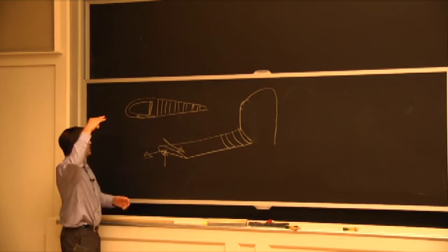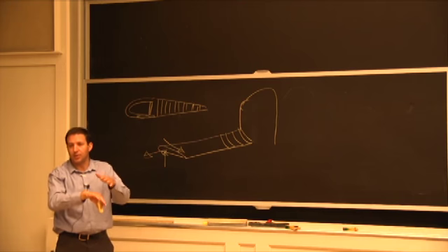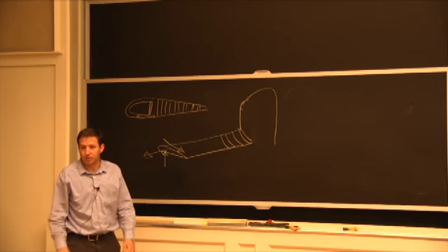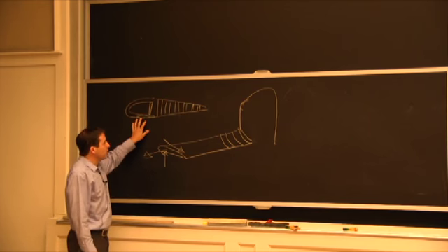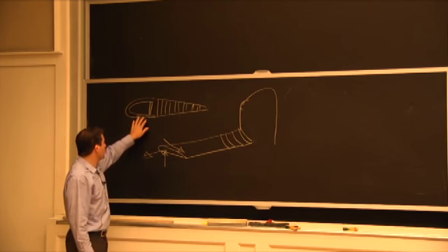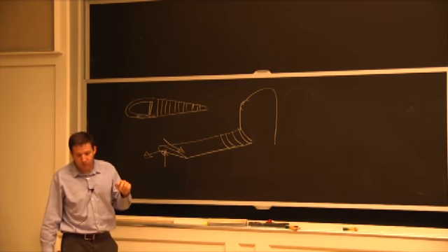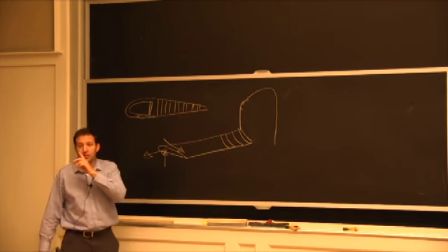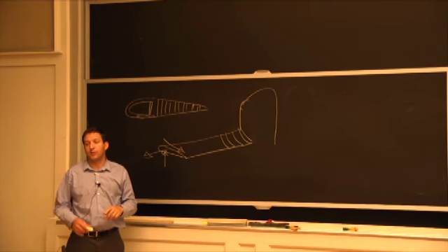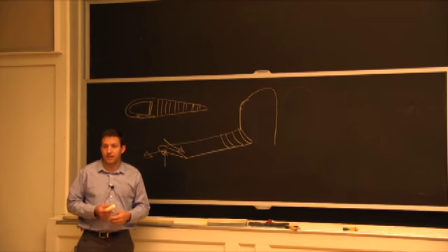If you were looking at a crack that would go this way, it would go a little bit between the laminar levels of the grain structure of the aluminum. So we can start looking at the material properties, specifically in this case, fatigue properties, although this is essentially exposed to the environment. So if there's any risk of an effect from salts into stress cracking, we also need to test for that.